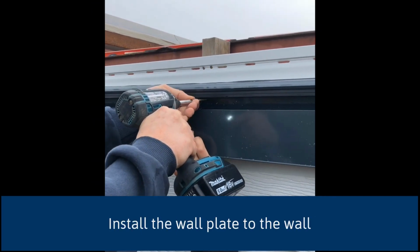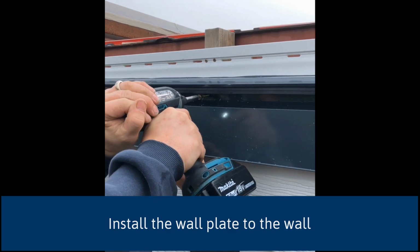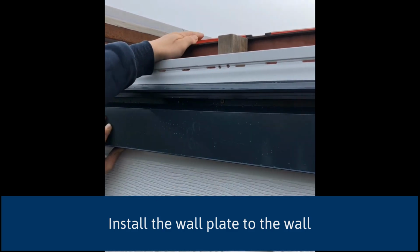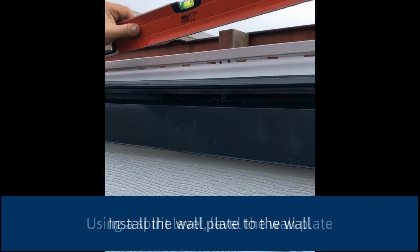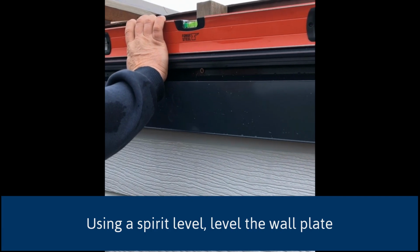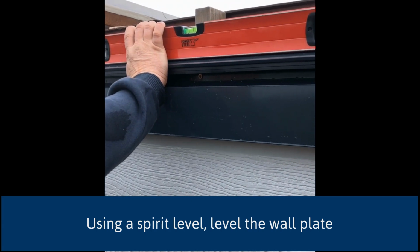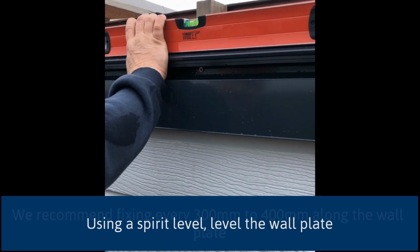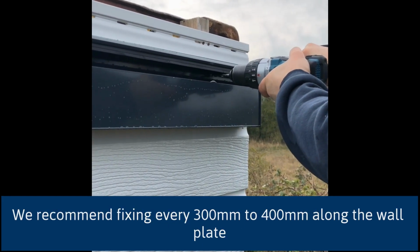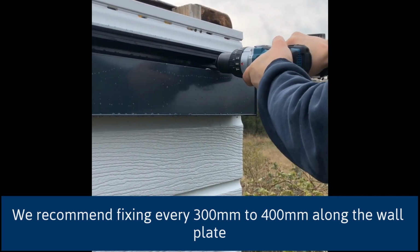Fix the wall plate. Using a spirit level, level the wall plate. We recommend fixing every 300 to 400 millimeters along the wall plate, depending on the fixings that you can obtain.